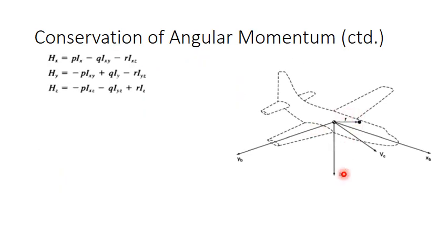If the reference frame is not rotating with the airplane, then as the airplane rotates, the moments and products of inertia will vary with time. To avoid this difficulty, we will fix the axis system to the aircraft, which is the body axis system. Back to Newton's second law.